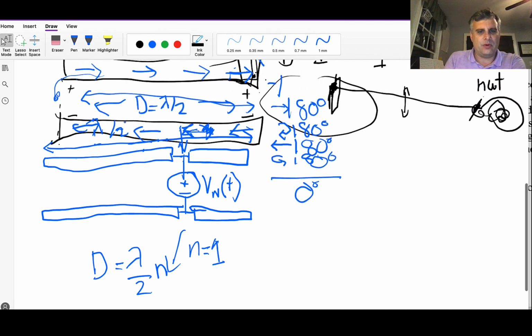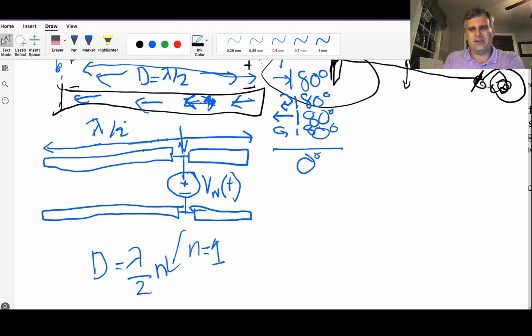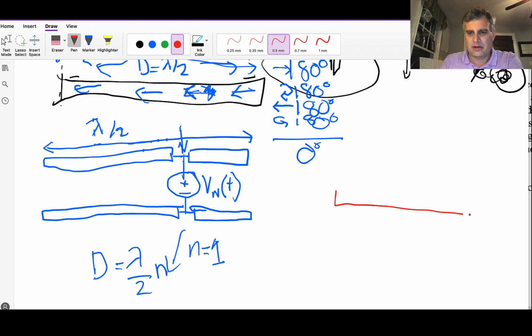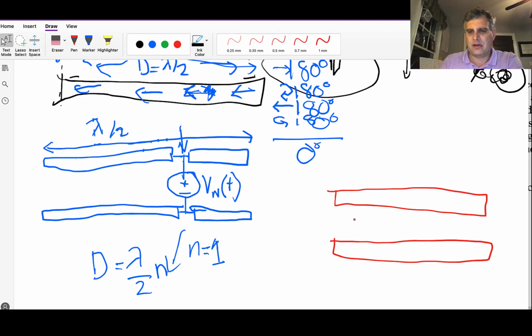Now, when we're studying standing waves, we have to recognize that this is what the current is doing. What the voltage is doing is something different. It still obeys the exact same resonance. But the standing wave is not a hump of current with minimum at the end. It's actually an inflection where you get maxima at the end.